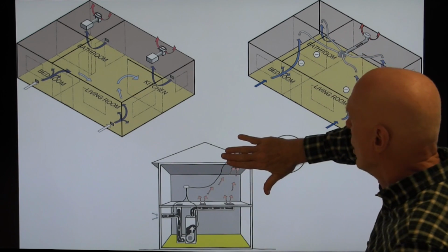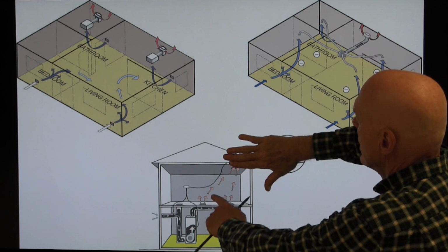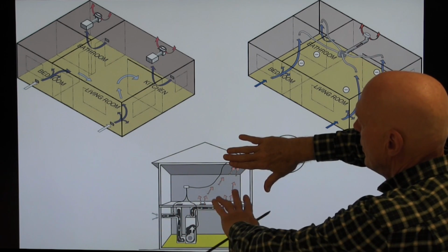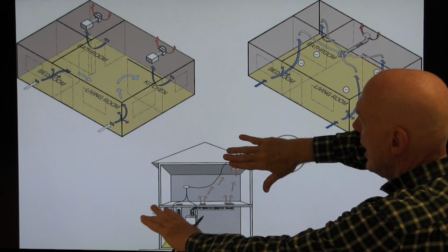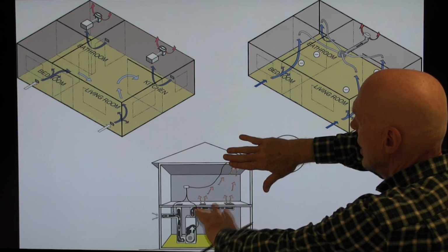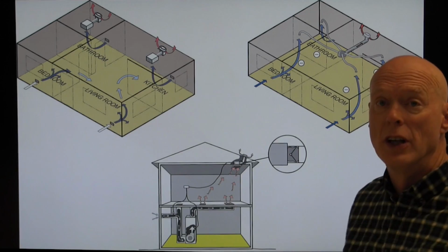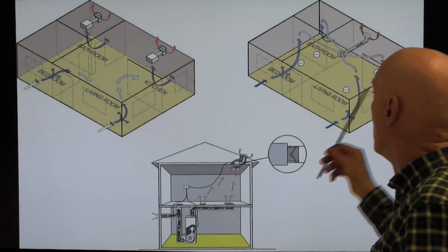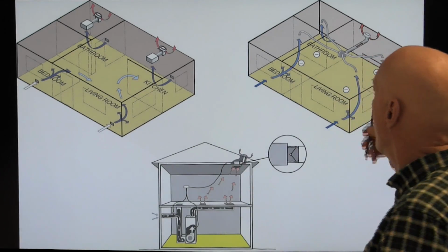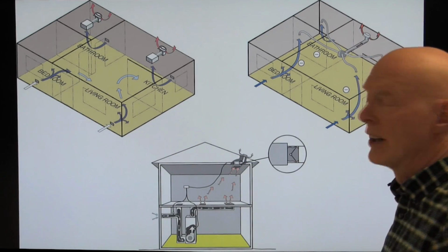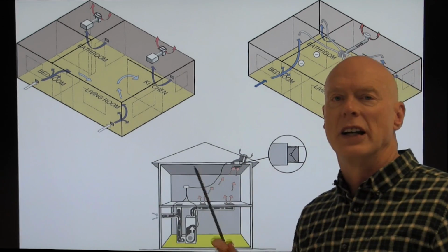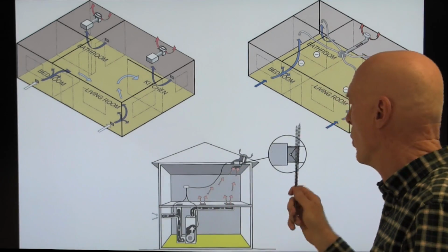And normally in this condition, we're hoping that the excess air that we've taken in is going to be exhausted through the air leaks, in the same way that we're expecting the air exchange from the outdoors in the exhaust-only systems to work.